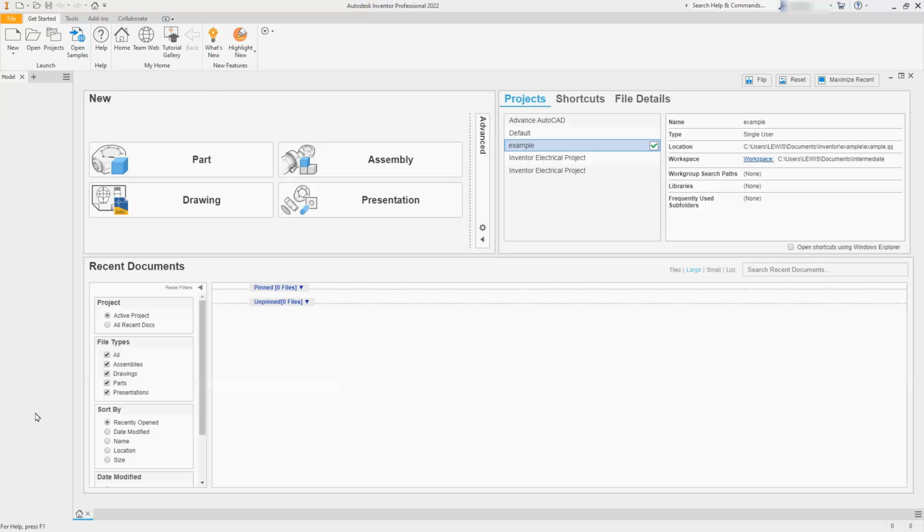Starting in Inventor, once you get it started, this is kind of the home page, and I'm using Inventor 2022. So the first thing that I'm going to do is go into the modeling application. But one of the things I notice about my drawing is that it's in millimeters. So if I go ahead and click the parts one, it's set up right now to use inches.